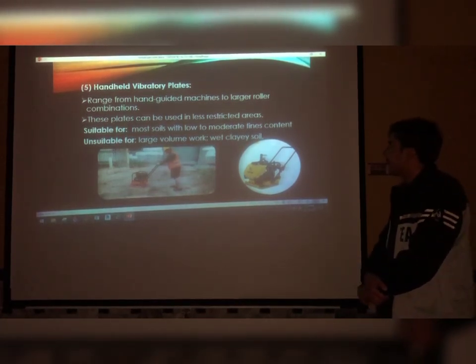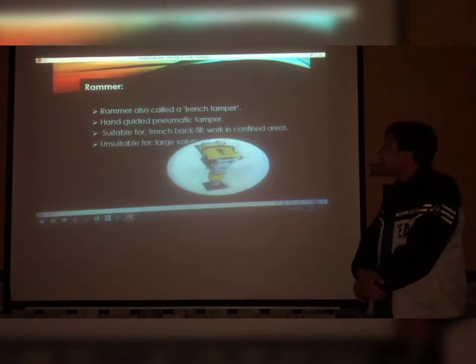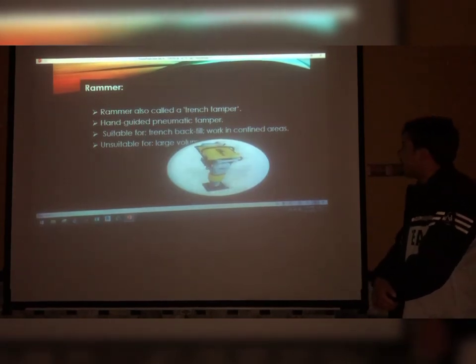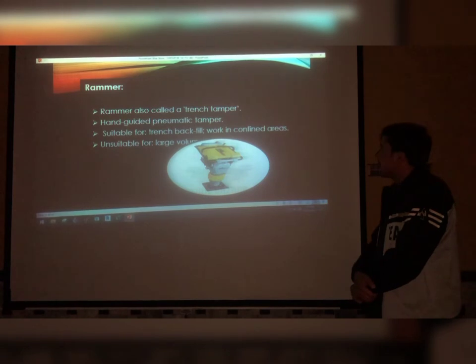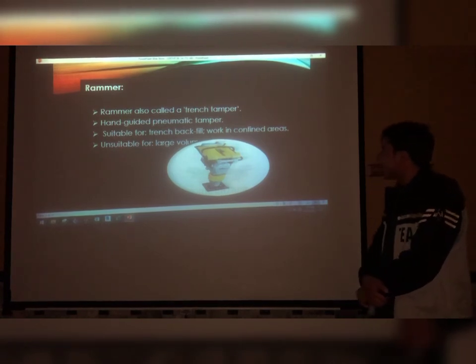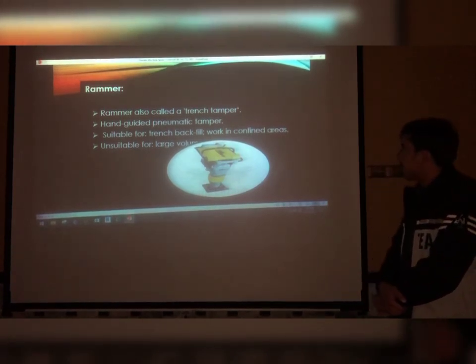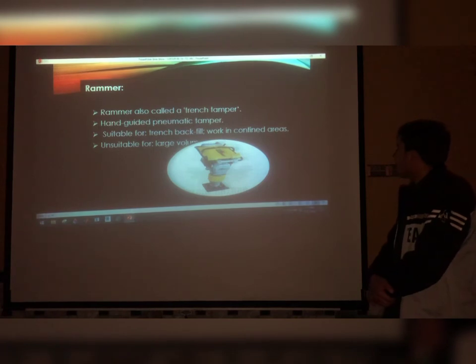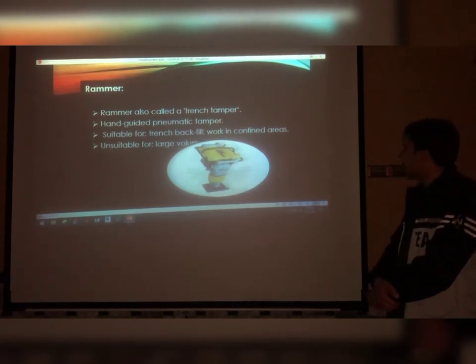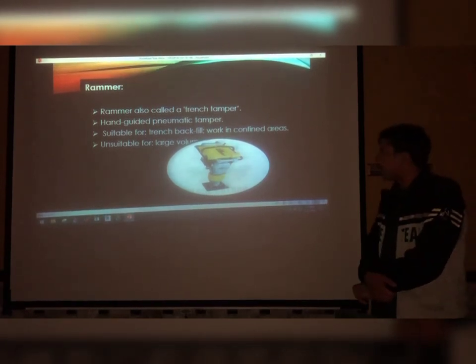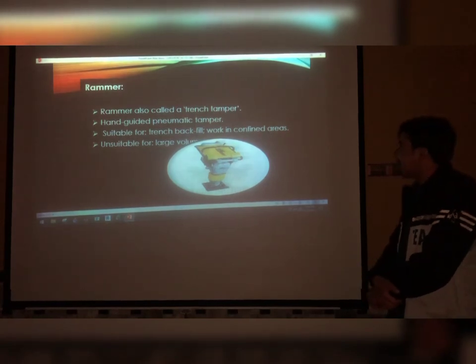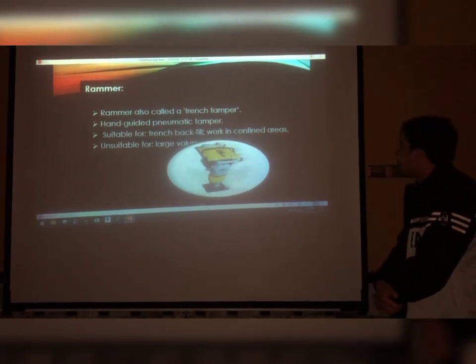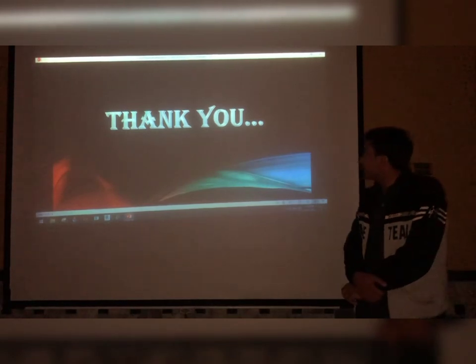The last one, rammers, also called trench tampers or hand guided pneumatic tampers, are suitable for trench backfills and work in confined areas like in buildings and rooms. It is unsuitable for large volumes. Last, thank you.